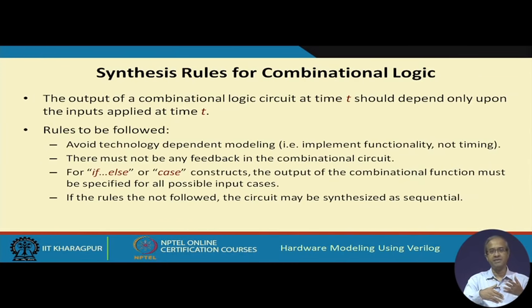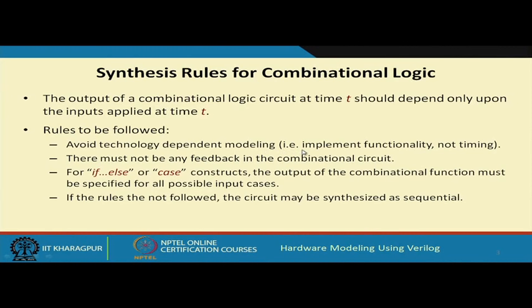But when you are synthesizing, your final delays will be dependent on the actual hardware where you are mapping, be it ASIC or FPGA. So, you do not have any control over the delay. You cannot say the delay is 1 or 2 or 3 nanoseconds or picoseconds. That will depend entirely on the hardware where you finally map your design.